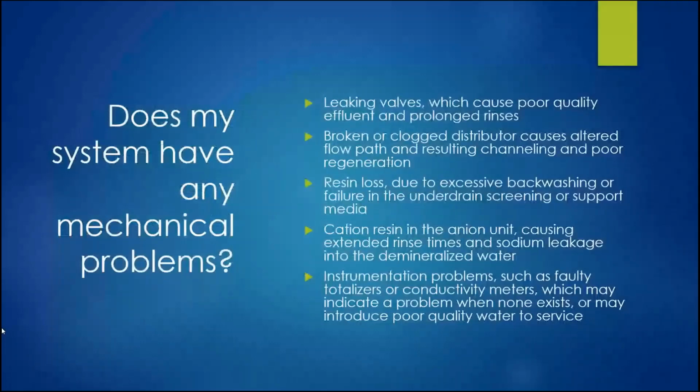IX systems can also suffer from mechanical failure, such as leaky valves, as well as damaged distributors or screening. Instrumentation problems can also falsely indicate a problem where none exists. Proper system operation and maintenance should prevent or minimize these occurrences.